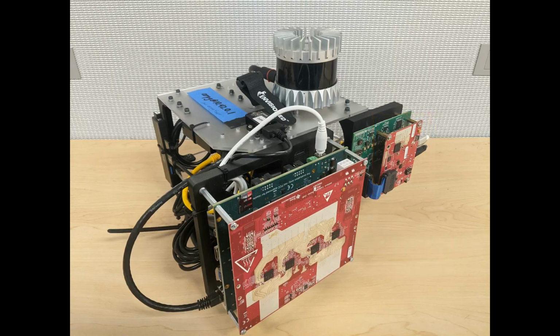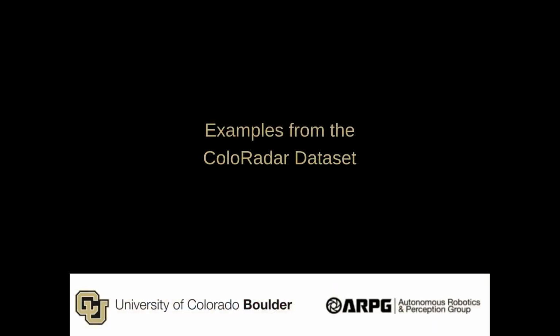The sensor rig also includes an Ouster 64-beam LiDAR sensor and a Microstrain IMU. The sensor rig provides synchronized measurements from all four sensors as it undergoes motion with 6 degrees of freedom in a diverse set of 3D environments. Additionally, we provide ground truth poses computed after the fact using global optimization of a LiDAR inertial pose graph. Here we provide short examples from our dataset in various environments.